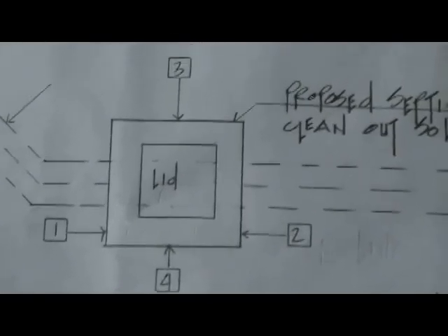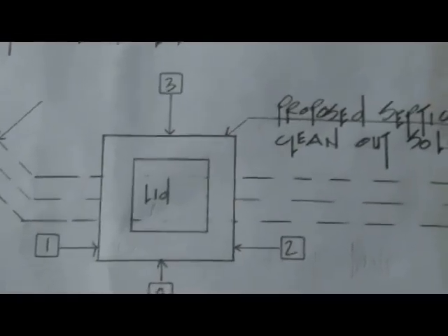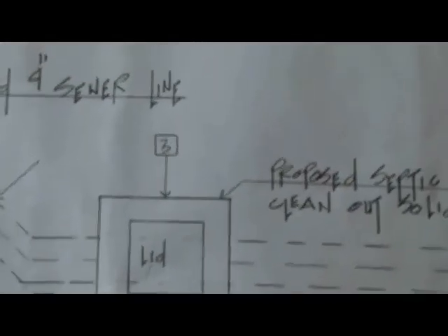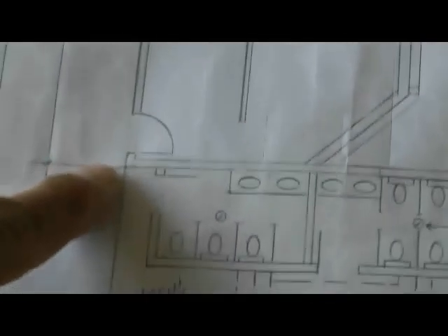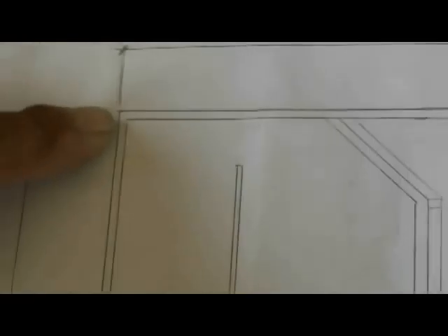My recommendation would be first to establish the building lines, and then from the building lines, which is like this corner here, where the bathrooms are, and then you'll go up to the north, that corner there, and then of course you're going to go to the east, that corner, and you're going to go down, and there's the main entrance, and then you're going to go down to the southeast corner. Now, establish those lines first.